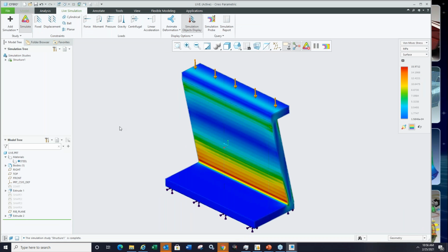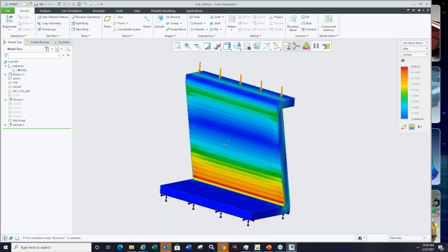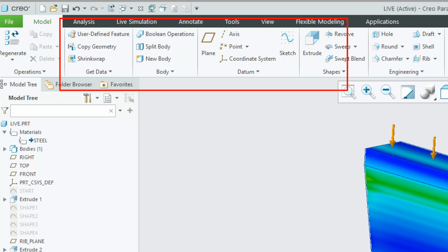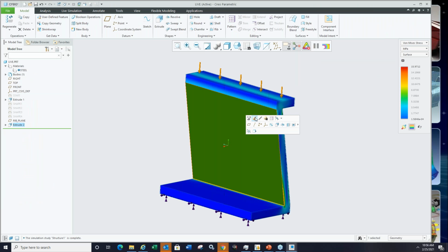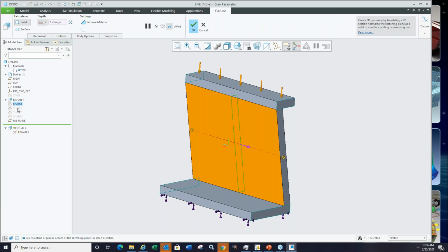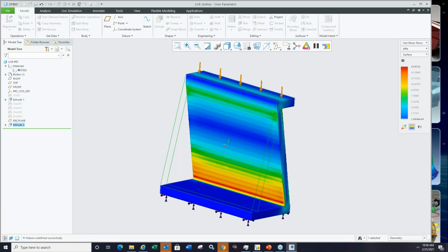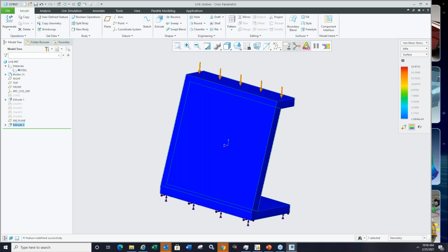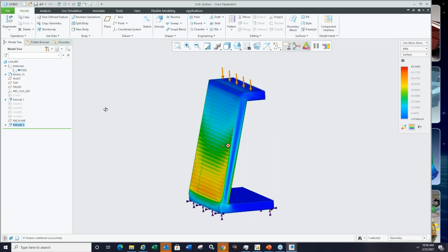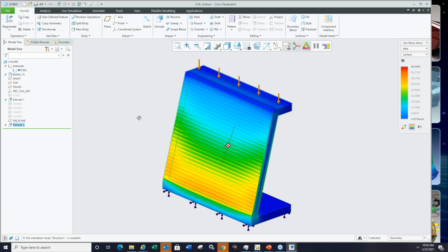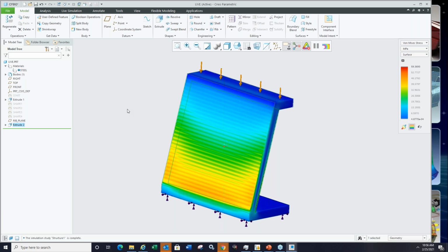I can go back to my design mode. I could be in a regular Creo modeling environment. I'm not even in another application or anything like that. And I could say, let's redefine this and, instead of this, maybe use this one instead. I middle click, and as soon as I change it, I didn't even have to hit regenerate or go to Applications and then rerun or show. It knew to go back to the blue color, and that's the power of GPU-based computing. It's using ANSYS proprietary voxel-based meshing, and we don't even get to see the mesh or anything.